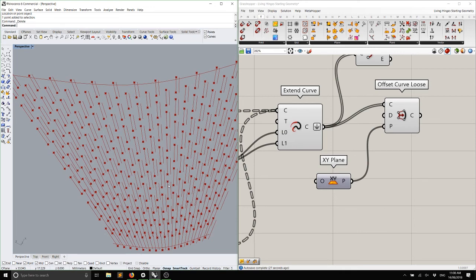Okay, I have a line on a plane, right? Like in 2D. So when I offset it, it's going to look like so, yeah? Like we're used to doing offsets like that. But if I have a line in 3D space, what plane does it get offset on? This plane? Yeah, but look, I can draw lots of different planes that line sits on, yeah?